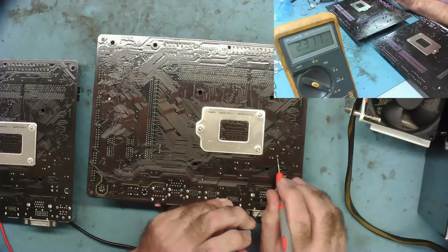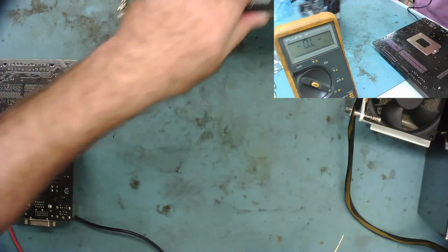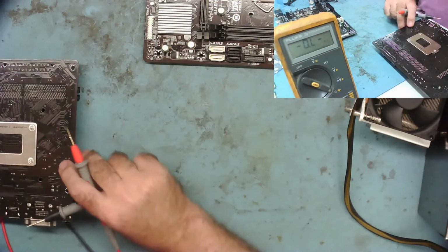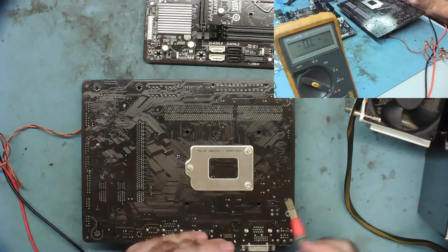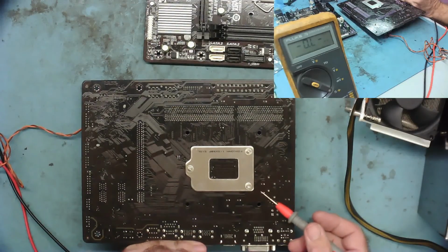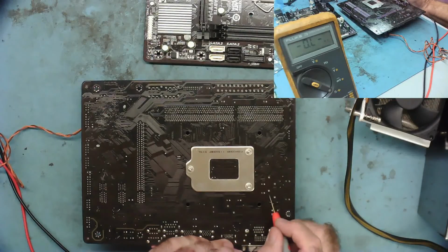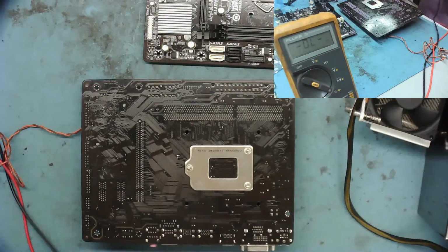Well, you can see what it's doing. It's reading kilo ohms and climbing. Yeah, that's the good board. Let's look at the one that's powering on and off. Yeah, which is the bad one. Yeah, this is the one. So again, we'll make sure the main vCore capacitors are discharged, and then we'll go to here. Yeah, it's doing exactly the same as the other one.